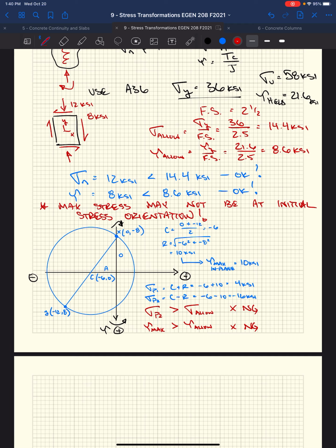I could take civil engineering into account, right? If it's an I-beam, something like a wide flange section, Norm Asbjornson Hall has tons of them, and they're spanning between 2 columns. When we design the flexural capacity of this, we use a factor of safety of like 1.67. But when we design the connection of this element to its column, it's anywhere from 2.5 to 5, depending on what that connection's doing.